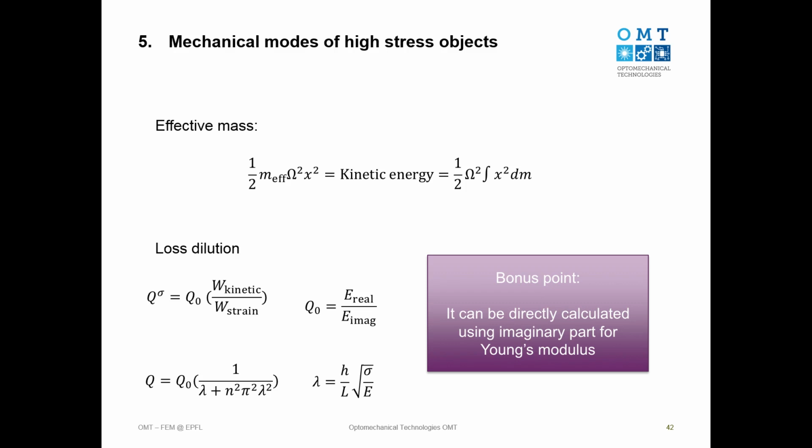So how do you calculate this integral? Calculate some values, for example, kinetic energy in this mechanical oscillator. If you want to do that, you come to this derived value, right click on it, and then you have different functions here. You can see you have average, integration, maximum, minimum, etc. To calculate the kinetic energy, you need to integrate the kinetic energy over the entire object.